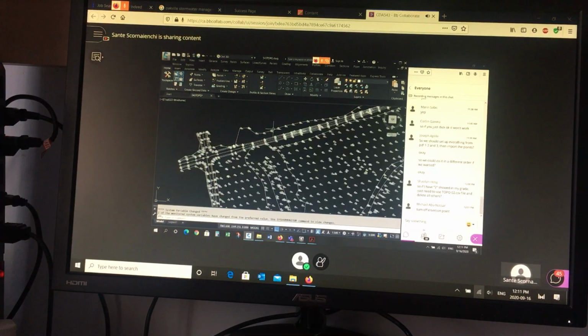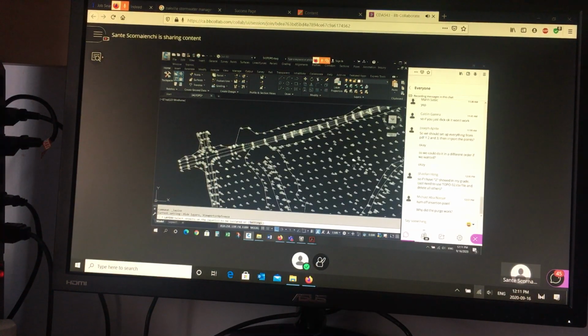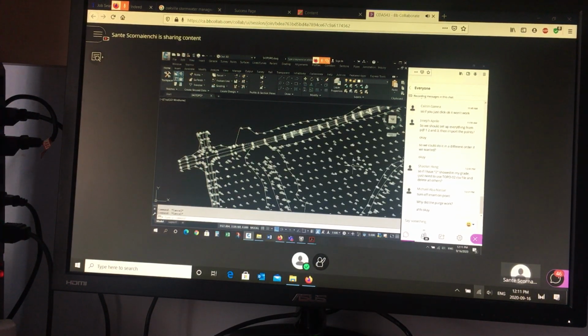So let's look at the center line. It was trying to insert the previous DXF from internally in the file instead of the external one. I don't know why. Okay. So before you bring it in, you should change the unit settings of the DXF first. It has to match meters to meters. Otherwise, it'll apply a unit conversion from feet to meters or meters to feet.